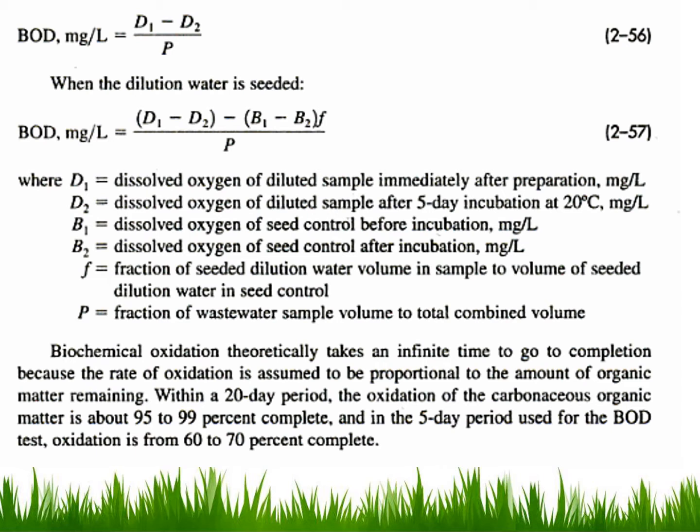But simply BOD is the difference in oxygen consumption, oxygen saturation, at the start of the experiment until 5 days. BOD test takes 5 days. So this is a question: why 5 days? We will try to answer it later on.